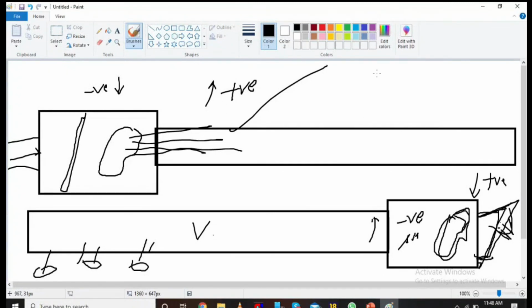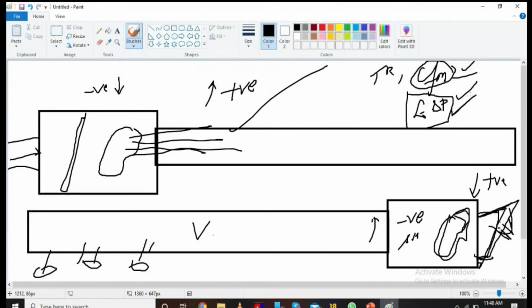By heat load, you will get tonnage and you will get CFM. CFM is only one part in the selection of a fan. The second part is external static pressure. You need to find these two to select your fan. For a non-centralized system, fine, only CFM is enough, but for a centralized system you need external static pressure, there is no other choice, you need to calculate it. At that time, I will tell you clearly about positive static and negative static.